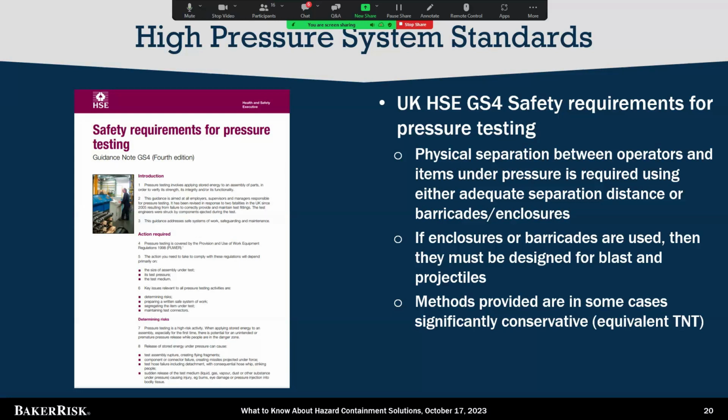It does provide a few methodologies in a reference document for how to quantify the hazards and design barricades, but it's found to be fairly conservative. What it does is it converts the stored energy of the pressure system to equivalent weight of high explosive in terms of TNT. And that tends to provide an overestimate of the peak pressure from a blast load.